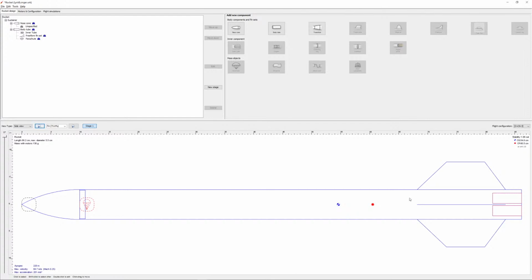And that's a really good thing because that allows us to still use Lyrid and have a higher chance of recovering it, but when the parachute ejection charge fires, rather than pushing this heavy nose cone out of the way, it'll light up a second engine. Now, one problem that I'm considering is the gases may not be enough to fill this entire tube. That's a probable problem that we will possibly run into, is the gases will simply not be able to fill up this full tube and light up the next engine.